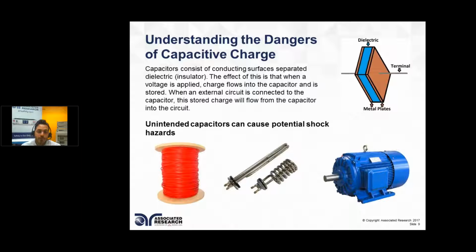I know in the production line, it's all about testing as fast as possible, but if you have these types of DUTs that come with a capacitive characteristic, it's beneficial safety-wise to add a ramp down feature.